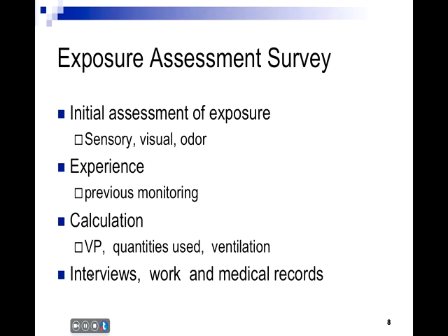And then I recommend that you do an exposure assessment survey. One of the first things that's important to do is to walk around the facility and take advantage of your sensory input, because certain chemicals have characteristic odors, and that can help direct where you're going to be sampling. If it's an aerosol you're sampling for, you can look around and see if there's any dust in certain areas and not in others, and that could perhaps help you direct your air sampling strategy a little bit more effectively. These aren't necessarily going to be the answers to how you need to do things, but it can give you some input that may prove very valuable.